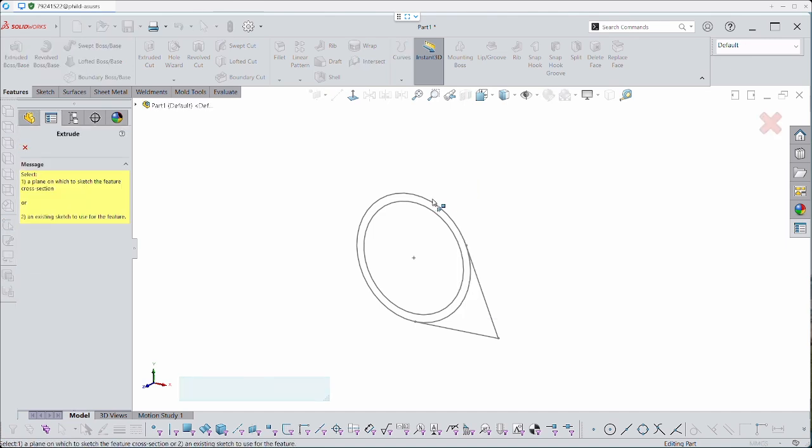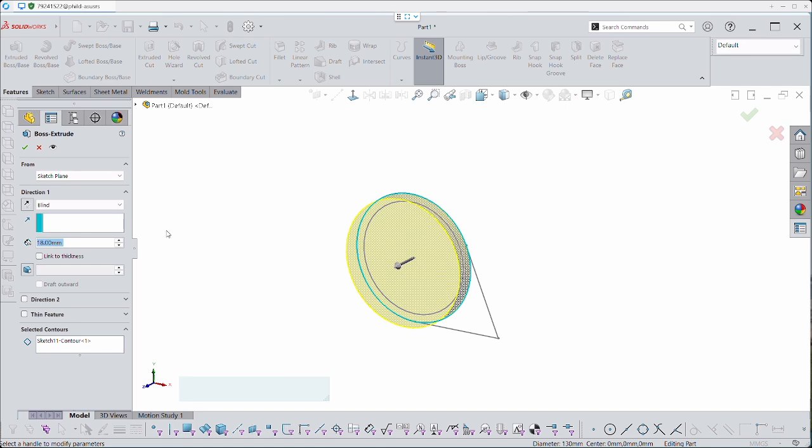Then you're going to be asked which sketch on this page, because you might have many, do you want to use? And so I want to use that one, right? What this does is it defaults to choosing one, or whichever one you selected, of the contours that you've sketched. So have a look at the bottom under the Boss Extrude Properties Manager.